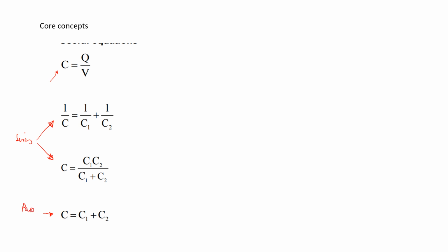The good thing about these equations is that for resistors, it's the opposite. So these would be for R in parallel. It's good because if you wonder how to work resistors out in parallel, you don't need to remember the equation. The bottom one there only works for two resistors. You can't do it for 3, but for 2 resistors you can use the bottom one. If it's 3, you have to go for the top one, the 1 over R.